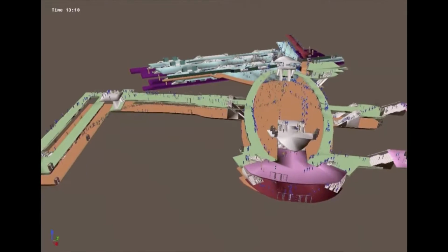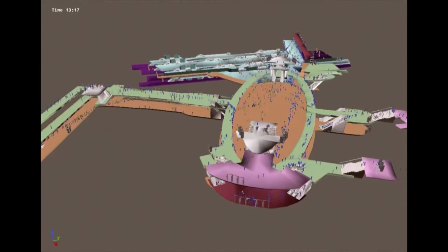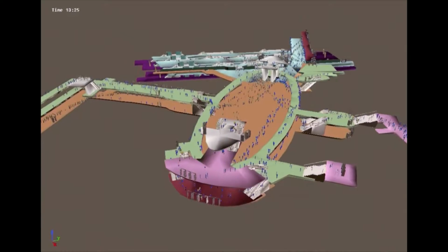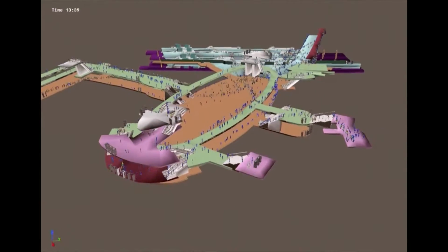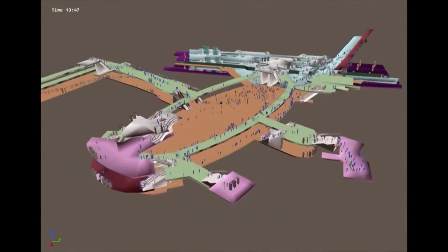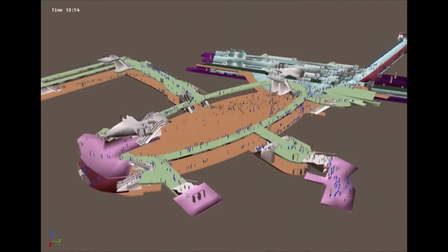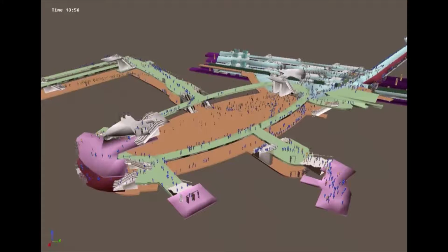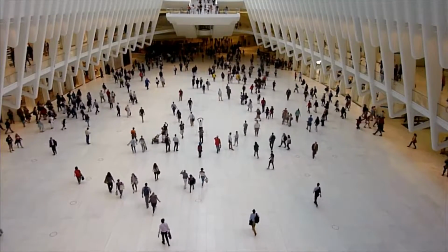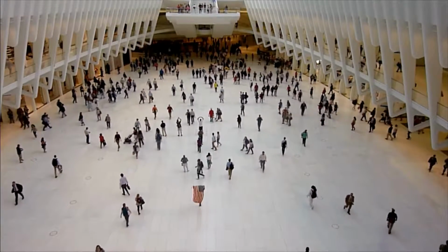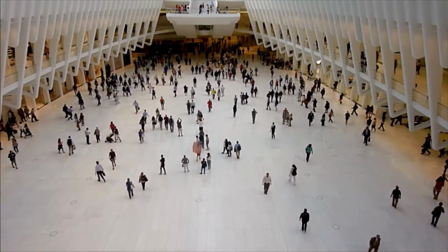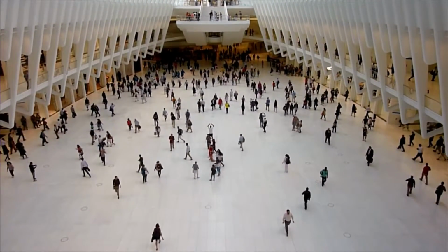So we did simulations. And this is early on. You got to understand, this is 2004 we did this. Working with a software program that's based on CFD analysis, we modeled pedestrian movement. And you can see how pedestrian movement is going through the space. You see all the concourse system there. Well, I was in the building Tuesday night, and I did this. Now, the model was the AM rush hour, which is the peak. This is the PM. The model was pretty damn accurate.